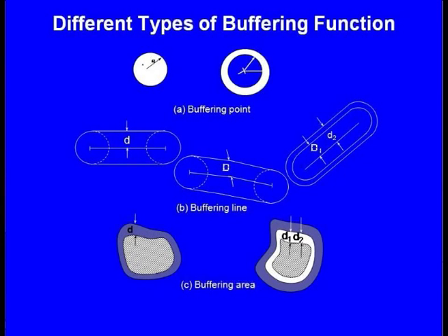The same technique could be applied for a line, wherein one can have a distance identified, that is, from a particular line a specified distance can be given, that is, that along a particular sewer line, houses which are 40 meters on either side would be allowed to drain their sewer into their main sewer trunk line.